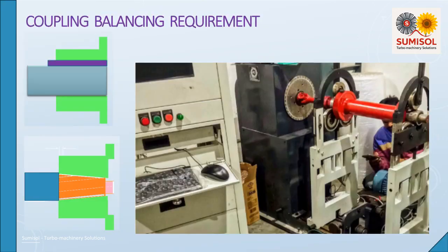Shaft couplings connect the drive and driven machine, installed in between them. These units are also balanced by the manufacturers. There are different balancing methods for shafts intended to be used as a shaft hub connection with a key. The distinction is made between half-key balance and full-key balance.